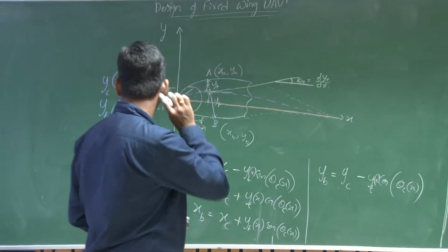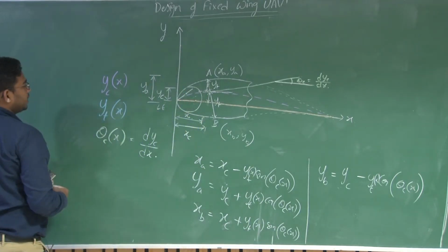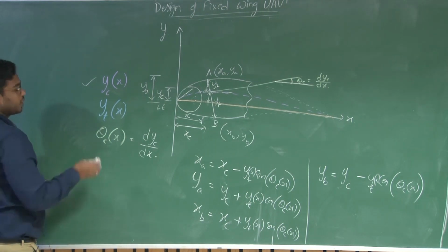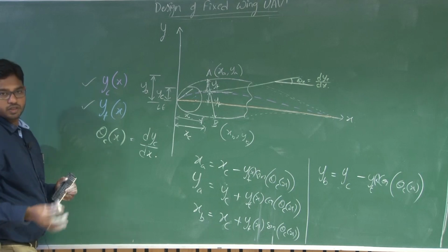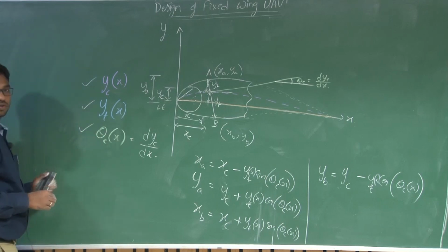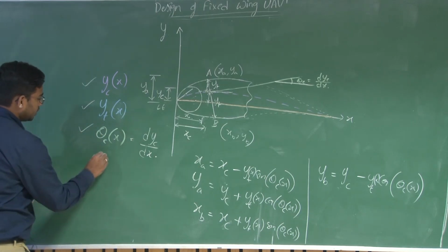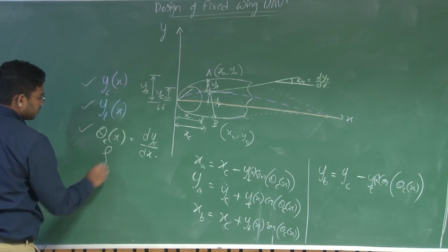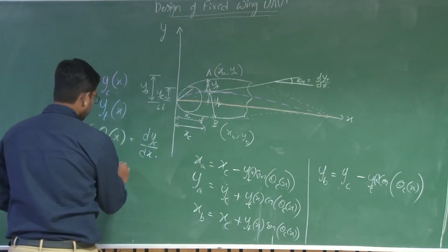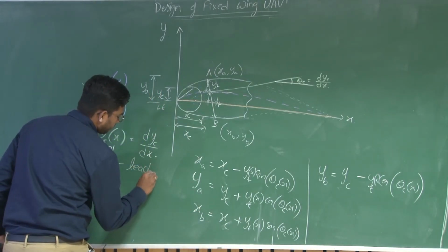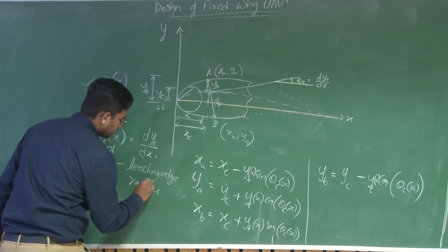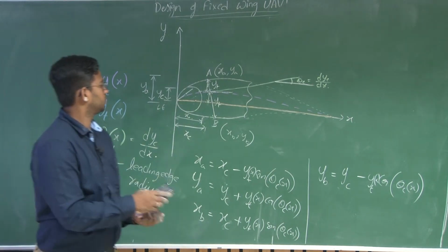Okay. So to define the aerofoil, what we need is the equation of the mean camber line, and the equation for thickness distribution as a function of chord, and theta, or the slope of this camber line, as a function of chord, and the leading edge radius, rho prime. Rho prime is your leading edge radius.